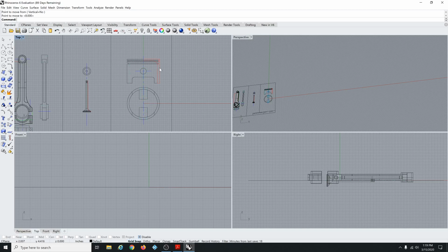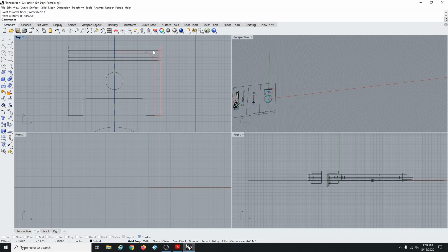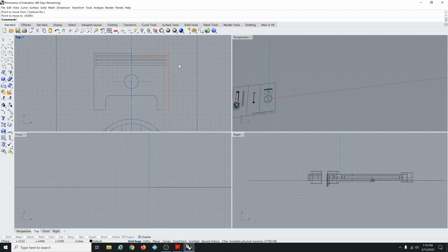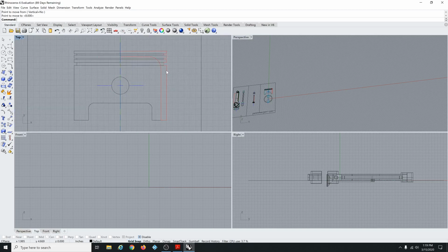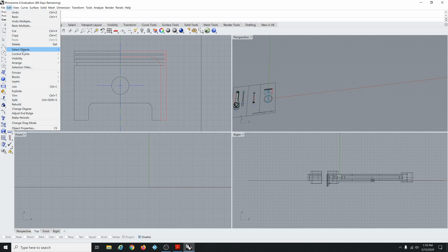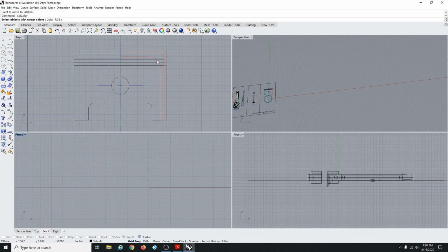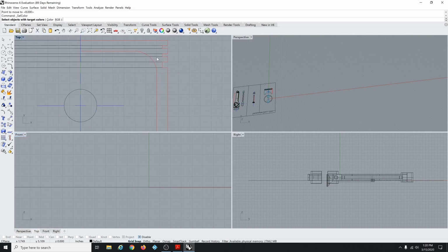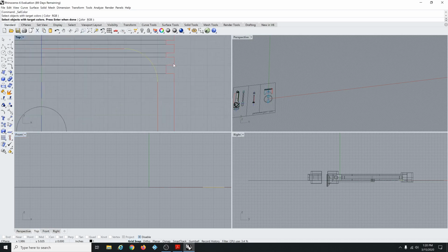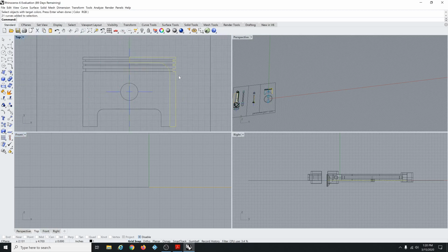So we're going to do another revolve. Here's a trick. See, there's a bunch of little red lines that are kind of ziggly in here, and you have to make sure you get all of them or it'll mess up. So Rhino has a tool that you can select objects by color. And it's asking you for a sample object, basically. I'll pick this, press enter. Now it's selected everything that's red.